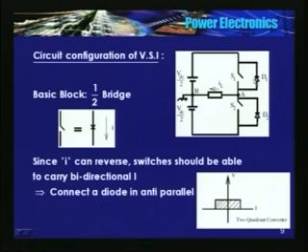So therefore, though you have closed the switch at that instant, that switch will not carry current immediately. It all depends on the circuit parameters. Therefore, from P to Q for an RL load, D1 is conducting even though you have closed the switch S1. So because of this, the gating requirement changes.